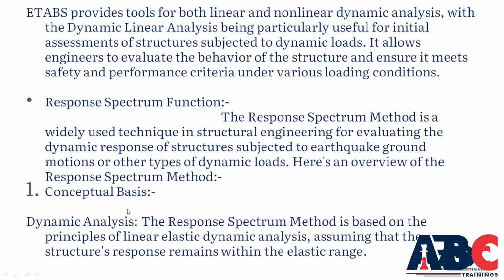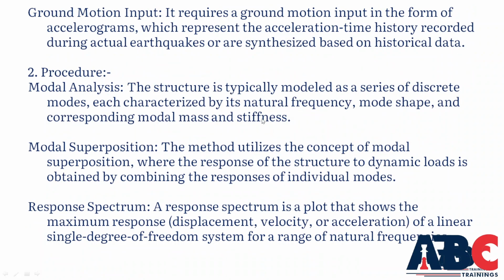First thing is the conceptual basis, that is dynamic analysis. The response spectrum method is based on the principle of linear elastic dynamic analysis, assuming that the structure response remains within the elastic range. Then ground motion input: it depends on the acceleration time history recorded during the actual earthquake. It is recorded by a seismograph. The Richter scale is a unit, and the seismograph is a device used to measure earthquakes.